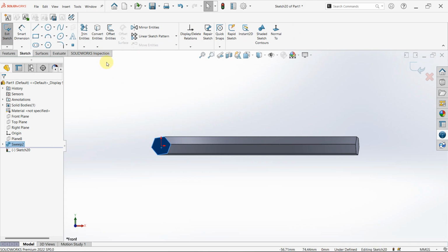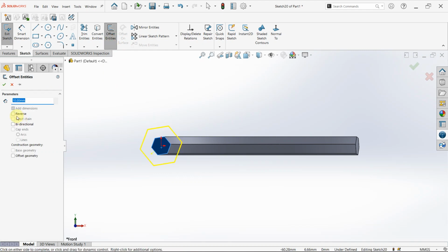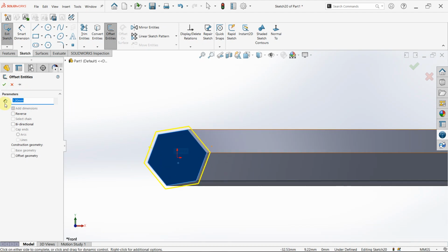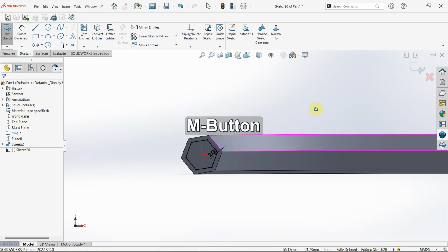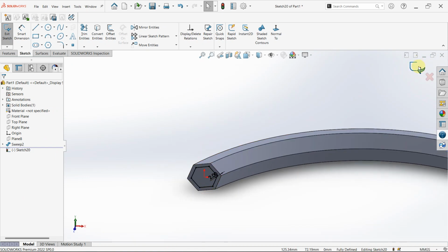So I can convert this sketch by either converting it or offsetting it. So reverse direction, let's say the distance between the offsetted one and the one that we want to create is 1 mm. You see them coming closer. So you reverse the direction to come inside. Or let's say the thickness we want is 2 mm. So just click and created that sketch. That's our profile.